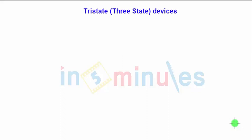In this presentation we are going to see the tri-state or the three-state devices. Generally we know only two states in digital circuits, that is nothing but logic low and logic high. So the states we know till date are logic low and logic high, but there is also a third state, which is known as the high impedance state or state Z.